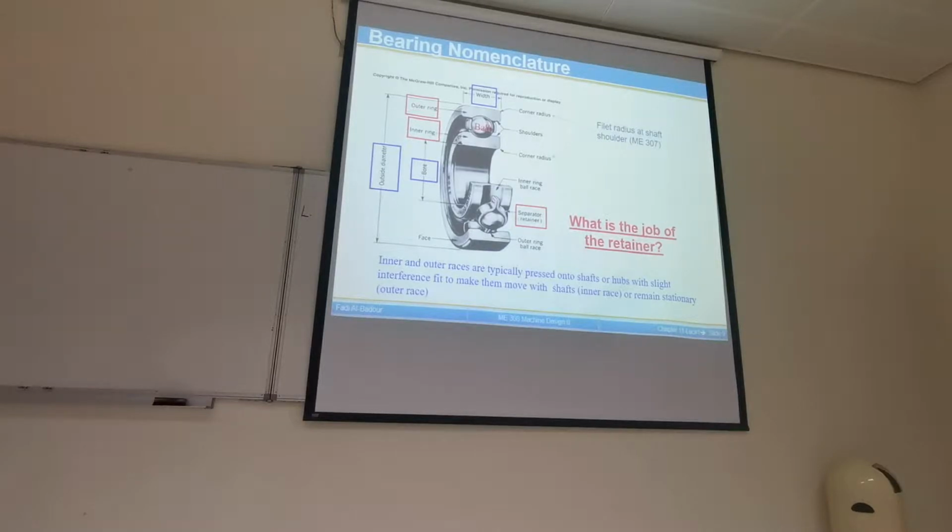Change the diameter only. Do you change the material? You go with a harder steel, for example? No, it doesn't work. Why? Because deflection is based on modulus of elasticity and second moment of area, right? Flexural rigidity, we call it. Those two terms, you multiply them together. So it's based on flexural rigidity.